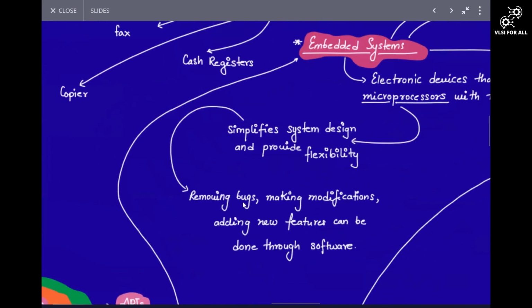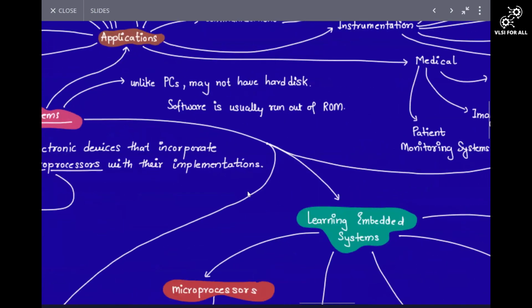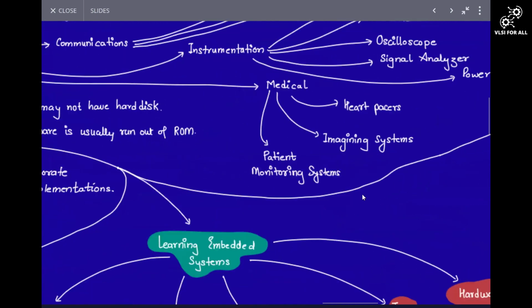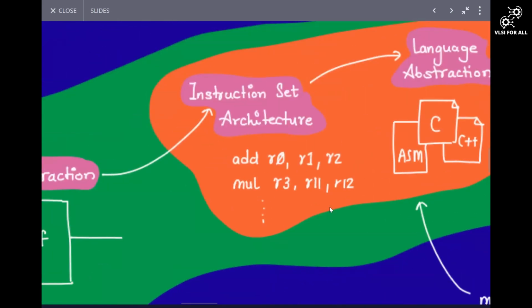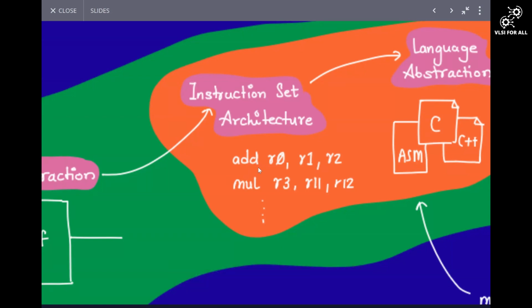And for the processor that you are using, you need to know its own tool chain. Every processor has its own tool chain, right? So let's say I have add, I don't have mul. My processor doesn't have mul, right? Your compiler should convert any multiplication C statement in terms of addition. But let's say another processor has mul in the instruction set. So the compiler can directly use the mul instruction instead of repeatedly adding. So if you are working with some processor, you also need to understand the tool chain that is built for that processor.